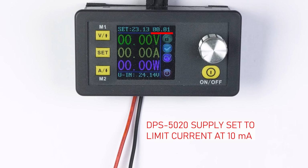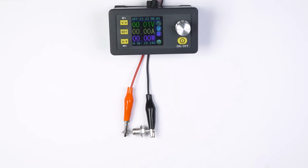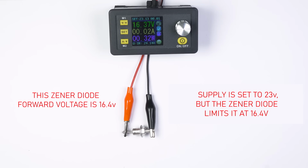As a result, by the way, we can come up with a simplistic voltage stabilizer circuit. As we can see, the lab power supply is set to 23 volts, but the Zener diode limits voltage at 16.4 volts. However, the output current strength of such a stabilizer will be very low, since current is limited by a resistor, and you cannot use it to power a mobile phone or a motor, for example.